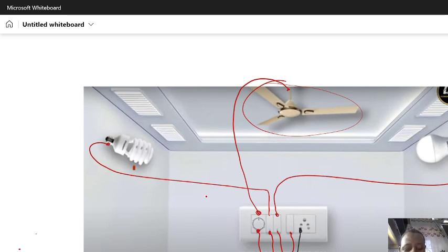Now remember, there is a socket that is controlled by a switch here to turn the socket on or off. So this socket will be connected from here to the other terminal of our socket. Why? Because this one I connected the neutral. Here I'm going to connect the live. I cannot connect the live from here, because as we saw in the previous video, this is going to be our earth. Someone else can connect the live to this one. If we connect it from this terminal, the neutral will be connected to here. It doesn't matter, because this AC will come in this socket. Now I connect it from this one to this one.